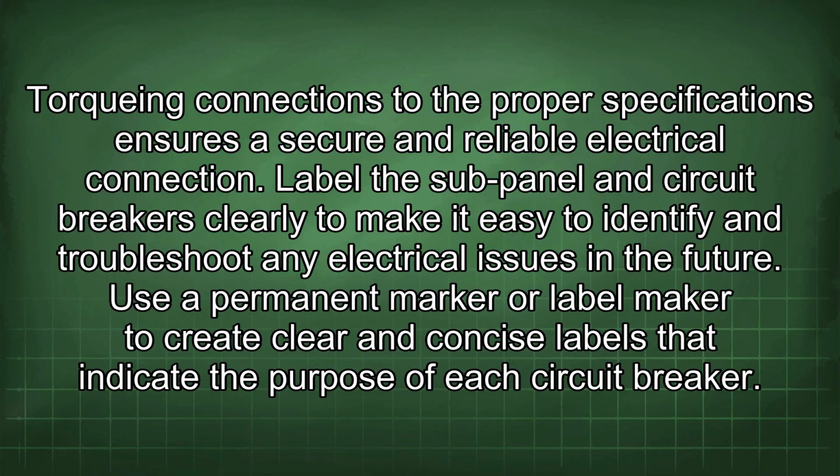Label the sub-panel and circuit breakers clearly to make it easy to identify and troubleshoot any electrical issues in the future. Use a permanent marker or label maker to create clear and concise labels that indicate the purpose of each circuit breaker.